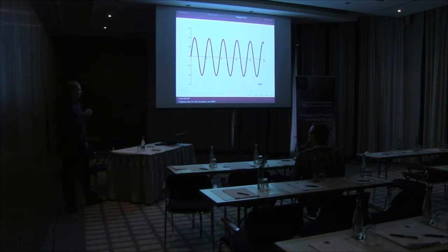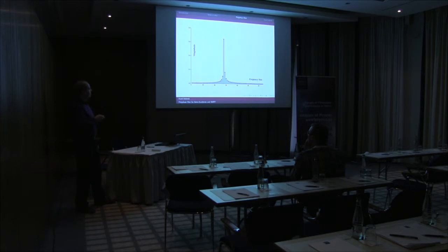I've used this. So this is our signal in the time domain. This is time, this is some magnitude. And this signal is basically a sine function with frequency outside one of the DFT frequency bins. So what we will get from our DFT transformation is something like this. This is the bin where the frequency is, but the problem is that we get these lobes here and here, and we don't want those because these lobes basically spoil our data, and that's highly undesirable.